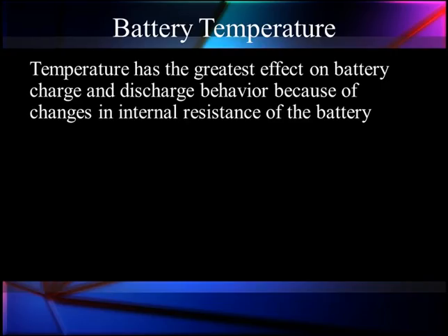But the temperature has the greatest effect on battery charge and discharge behavior because the battery changes in internal resistance with temperature. If the battery's cold, internal resistance goes up. Now we said battery performance decreases, chemical activity slows down. We've got a lot of words we use. What we're really saying is internal resistance goes up with a cold battery. That's why we have bigger voltage drops.